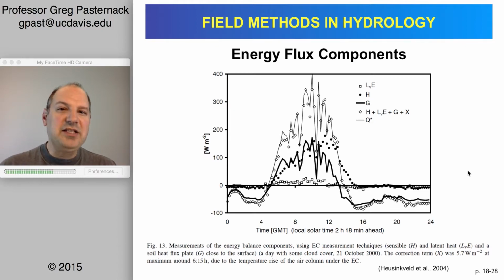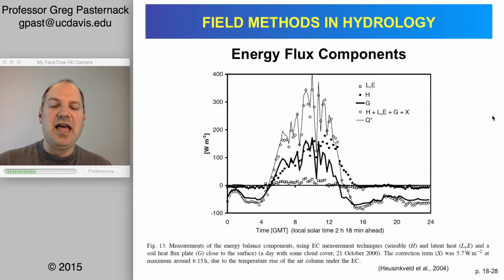Then you go to transpiration, and sap flow is the go-to for that. You can put evaporation and transpiration together either with an atmometer with the right cover or with a lysimeter. And then finally, you can use an energy balance approach to estimate evapotranspiration by putting relative humidity and temperature sensors above the canopy at set heights, and also looking at net radiation.